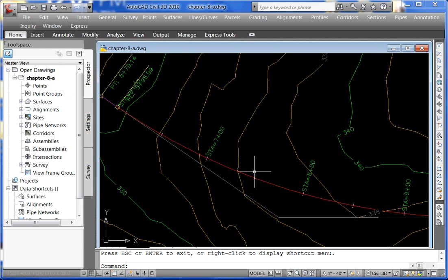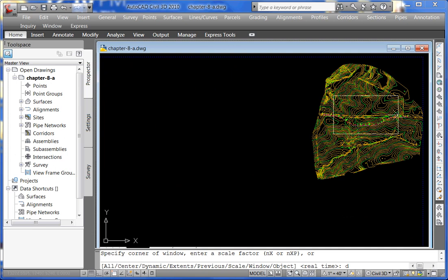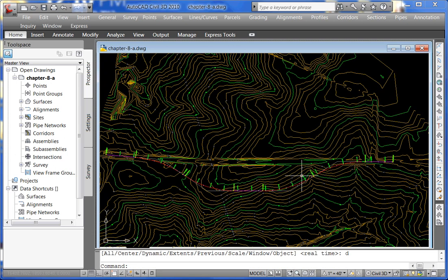And we're going to be asked about this tick later on in a very important test that comes up at the end of the quarter. So we need to know that that's a half station. And if station 700 to 800 is 100 feet, you can guess correctly what the length is between the 700 and the half station, 750 obviously. So you need an alignment and a DTM in order to create a profile view. That's our first step: we need to create a profile sampling off of the existing ground, and we're going to set that profile view up here somewhere in the right hand corner.